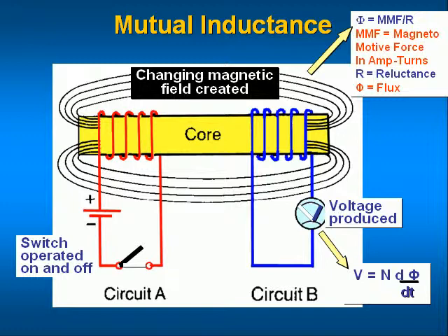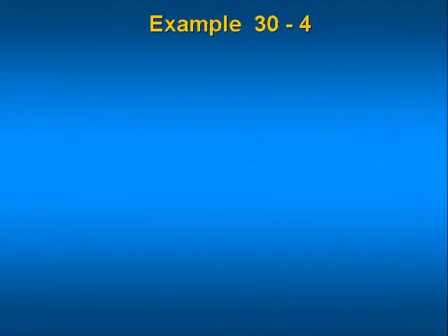An easy way to determine if an inductor is open or shorted is to make a DC resistance measurement with an ohmmeter. Normal resistance values depend on the wire size, the diameter, the number of turns, and the length of the wire that makes up the inductor.